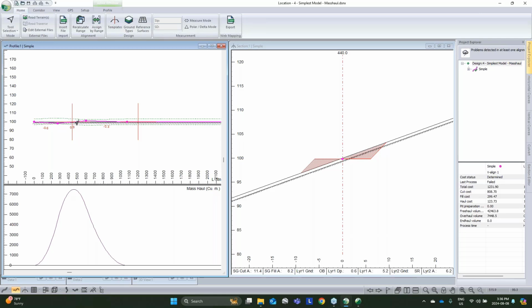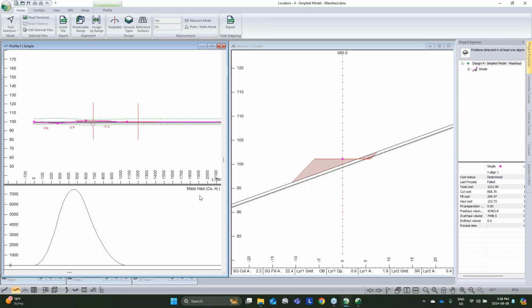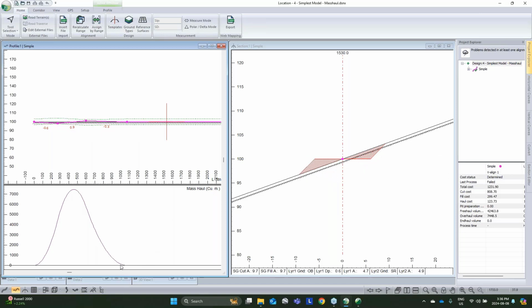So 0 surplus, and at that 0 surplus mark, the mass haul is going to be flat. So if you're in true cut and fill, if you are along a surplus to start and switch back to cutting and filling, your mass haul is just going to be level or flat. Now, as we go to a point where we're filling more than we're cutting, that mass haul line is dropping down. And then if we have something like this, where we're back to 0 and just flopping it from one side to the other, we're following along there.